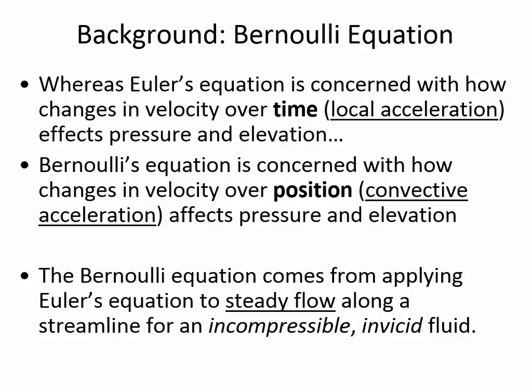All right. So the restriction of applying Bernoulli's equation along a streamline means that if you started here at the top part of the section before the pipe had contracted, you couldn't apply Bernoulli's equation at the bottom part of the pipe later on downstream. We assume that flow is going here from the left towards the right. We couldn't choose this as location 1 and location 2 because they're not on the same streamline. And we'll get into why that is a little bit later. But for Bernoulli's equation to have any predictive power, we have to apply it along the same streamline.